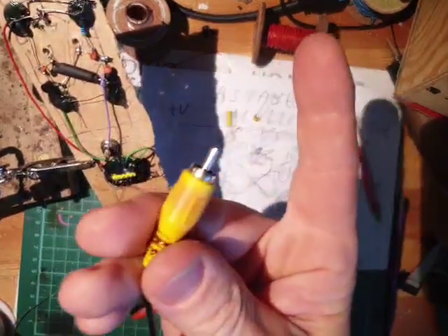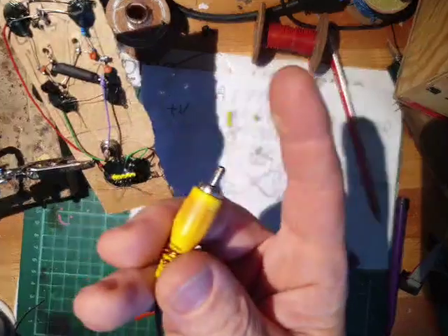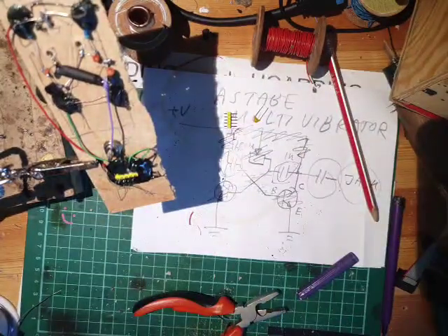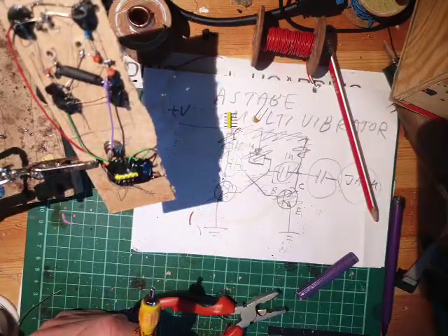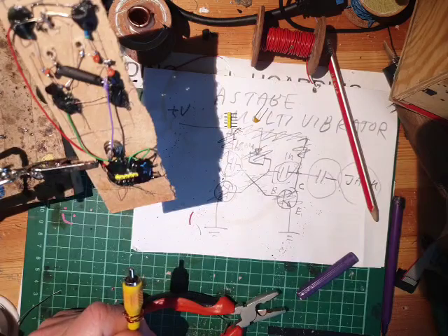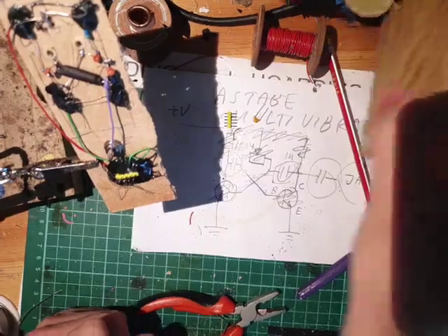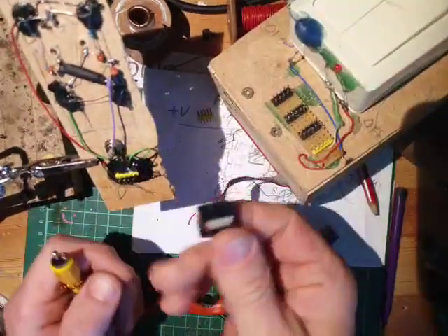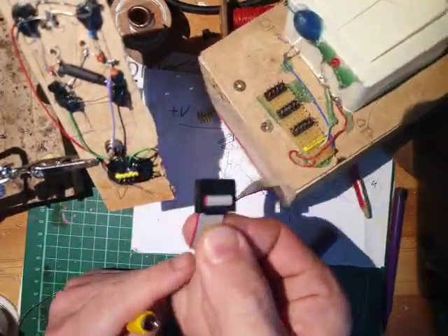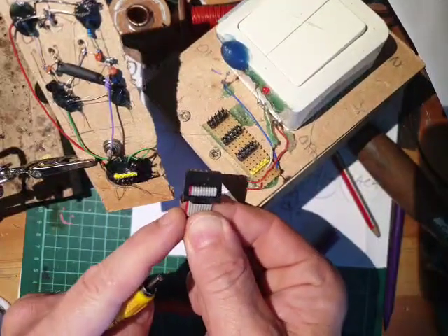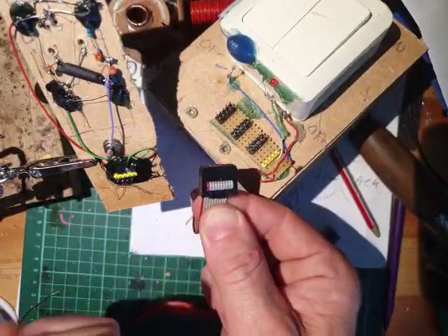So first thing first, amplifier. Make sure when you test a new circuit that you have no idea how loud the signal will be, that you turn down the volume almost to nothing. Then plug in your voltage. Remember that red wire on this cable means negative 12 volts.